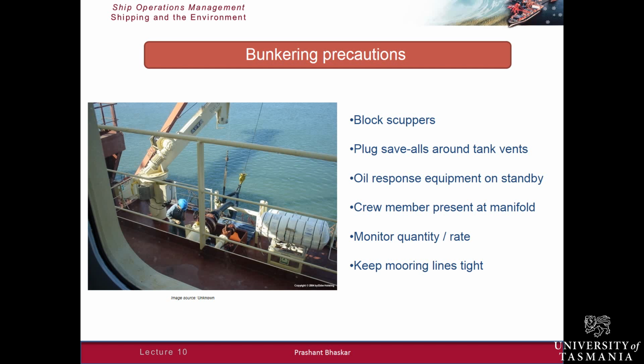Making sure that the oil response equipment is on standby, so that could be special chemicals. On very, very small boats or small fishing boats, it could be kitty litter, that can be used to mop up oil as well. Bunkering operations should always be supervised, so there should always be a crew member present at the manifold where the oil is coming in.